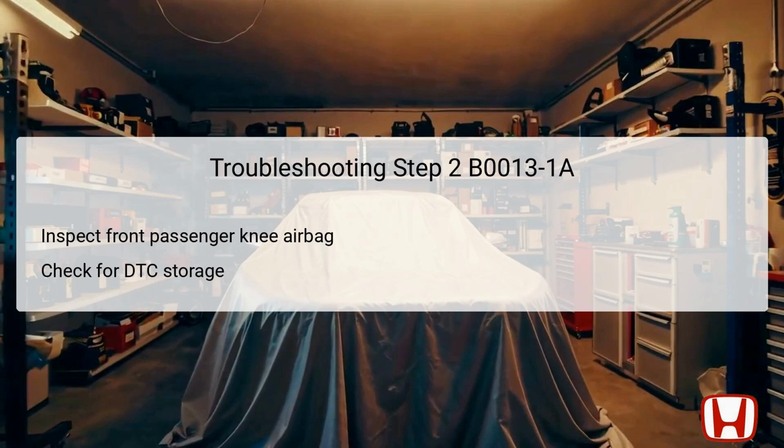If DTC B0013-1A is not indicated during this inspection, it suggests that there may be a malfunction within the airbag itself, necessitating replacement. Conversely, if the DTC does appear, it indicates that additional components associated with the SRS system may require troubleshooting or electrical continuity checks. This step is fundamental to discern whether the knee airbag or related components are causing the